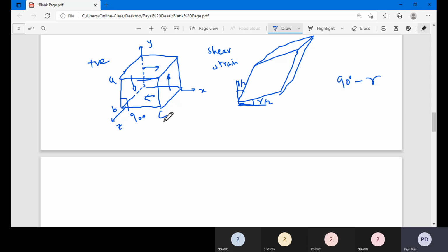When do we define the shear strain as positive? 90 minus gamma. Similarly on the opposite side, 90 minus gamma. But for sides AD and AB, it will be 90 plus gamma, right? Because this is 90 degrees here, so this whole angle will be 90 plus gamma. Then this is positive. Now what will be the effect of negative? The reverse. So the angle between AB and BC, imagine how it will distort, in the opposite direction. It means this side will increase like this. It will be something like this. This will be the distortion that has taken place.